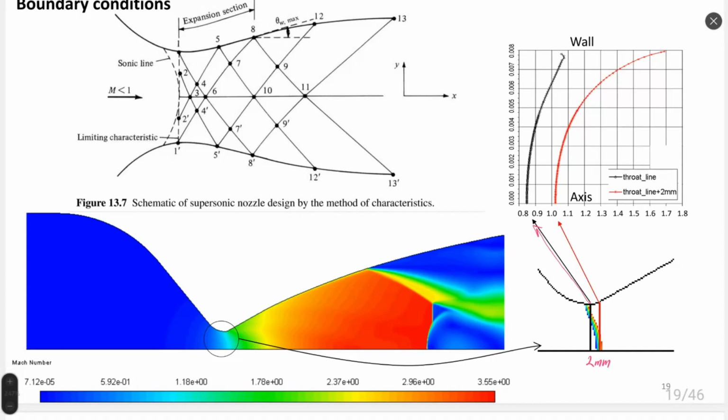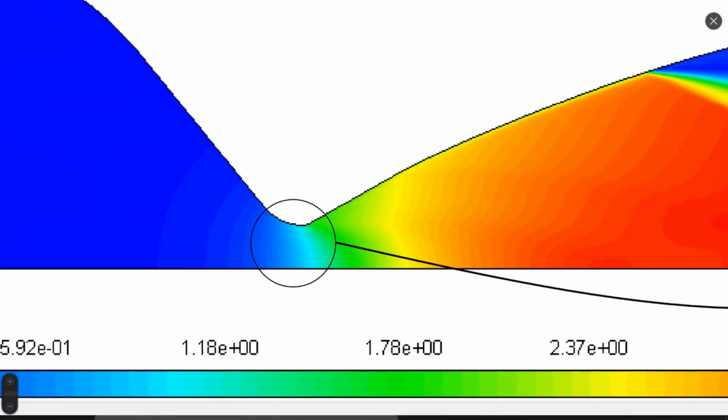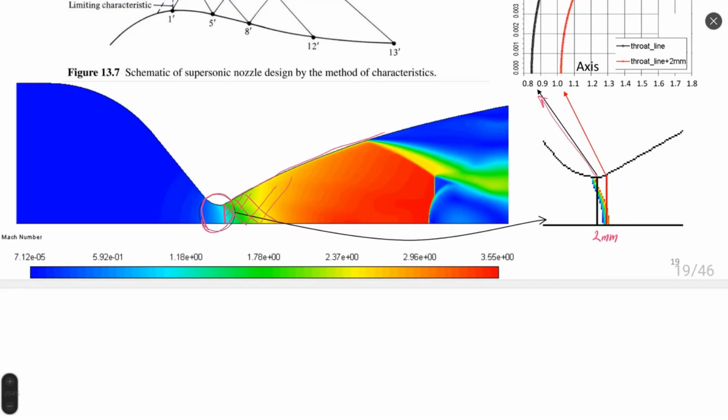Or the third case, we can guess some value of Mach number on the throat or distribution of flow properties on the throat, or we can just simulate this region here to find the Mach value distribution. And after, calculate by method of characteristics several, many cases, right? Profiling this nozzle and putting it in a CFD method to validate the method of characteristics.